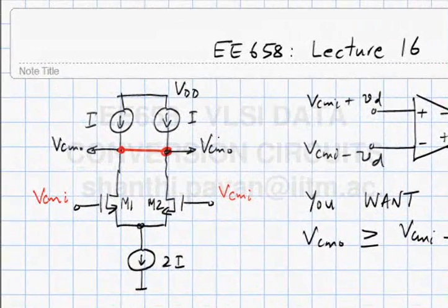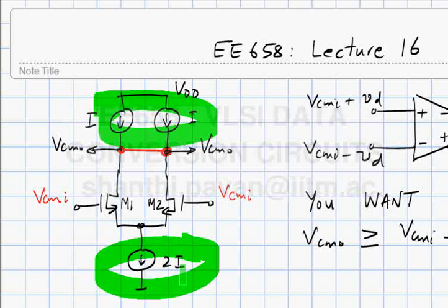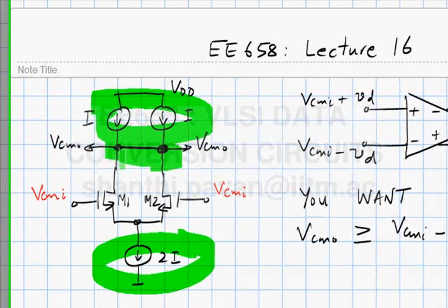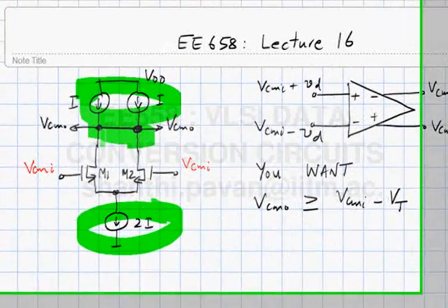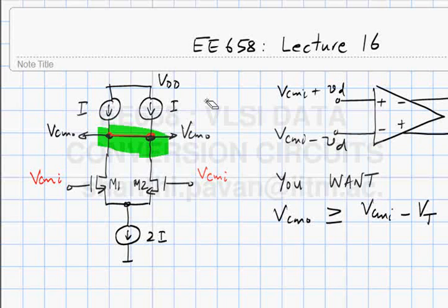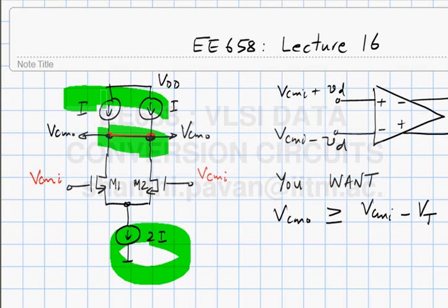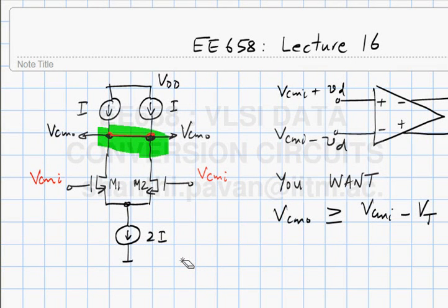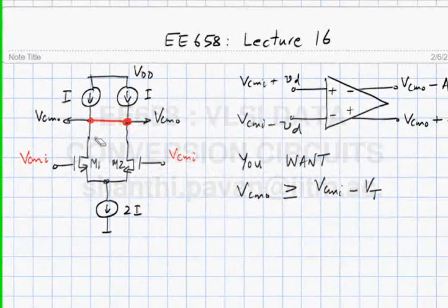So what is the solution? The problem was that this 2I and this 2I are independent. If they were made dependent on each other, then you'd be able to make that voltage stay at a constant potential without going either to ground or to VCC. You have two current sources. There are many ways of making this dependent, for example, you could make this one dependent on this one, or vice versa. I'll take a simple example where I'll make the top current sources depend on the bottom one.